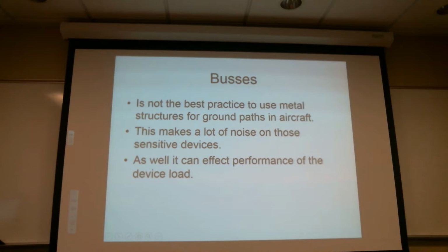And so just after it got out of warranty, it would start becoming a high resistance. Well, the ignition unit would figure out a way to, instead of going to ground, since it lost that, go through the coil of the relay back onto the positive side of the circuit, across over to the headlight relay, and back through the headlight relay coil to ground, which would cause enough energy to activate the headlight relay. Once the headlights would come on, that would create enough of a power drop in this already weakened circuit that the ignition would shut off. So the customer's complaint was, I was driving along and the high beams came on and the engine died.